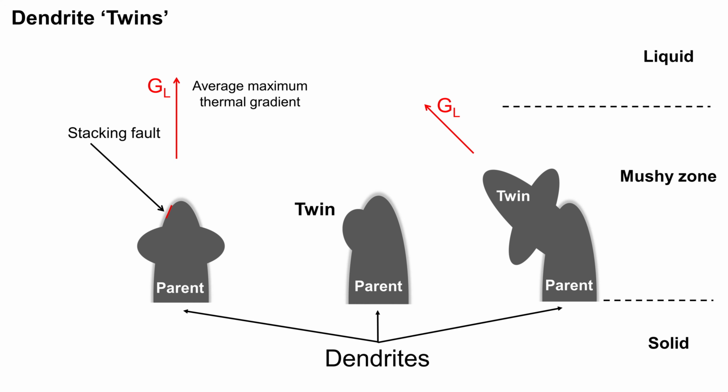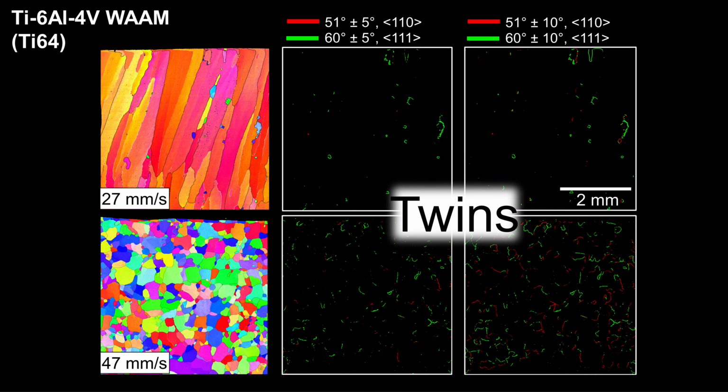However, since these stacking faults would tend to form with lower energy atomic arrangements, a few types of stacking faults would dominate, which maintain regular orientation relationships to the parent dendrites they formed from, which happen to be the same as those for regular twinning in beta titanium. And these are the twin orientations we're suggesting we've detected between the equiaxed beta grains in the EBSD maps. This would explain why our Hunt maps are wrong. The solidification theory Hunt used for the columnar and equiaxed conditions just isn't relevant anymore.